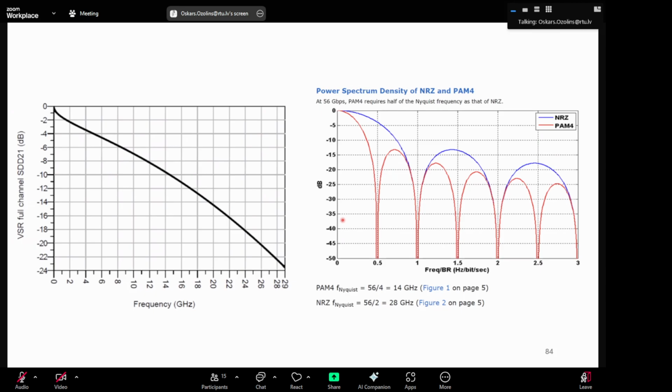So that's why industry has been looking into this, not only PAM2 but PAM4, and recently PAM6 and PAM8. It's a big optimization problem which modulation format will be next for these intensity modulation direct detection systems, to enable, for example, 400 gigabit net rate systems on a single wavelength in O band.